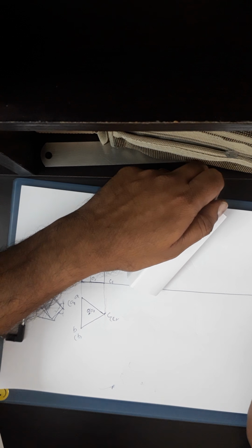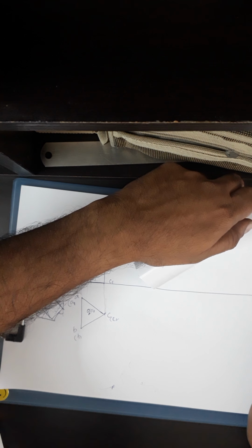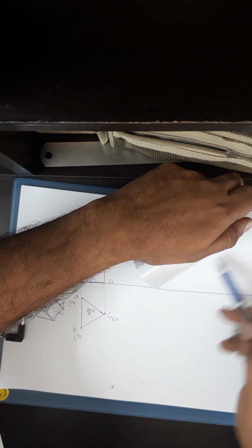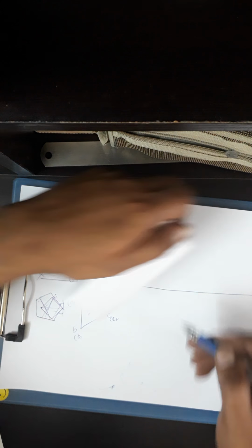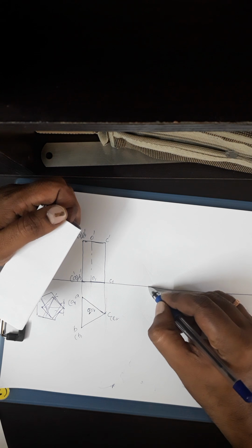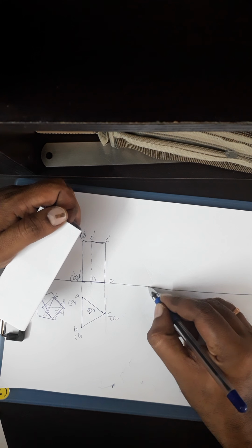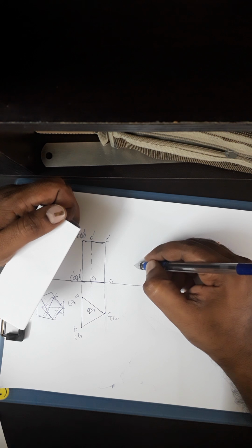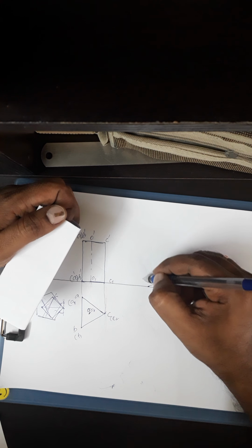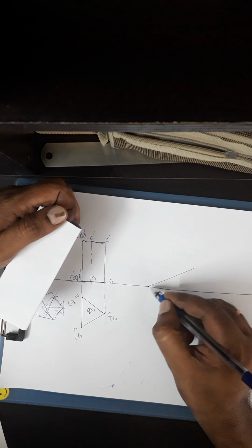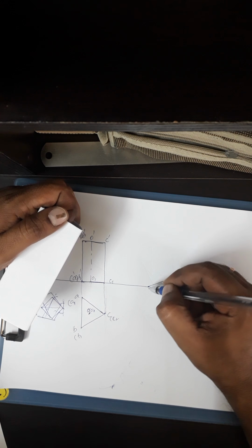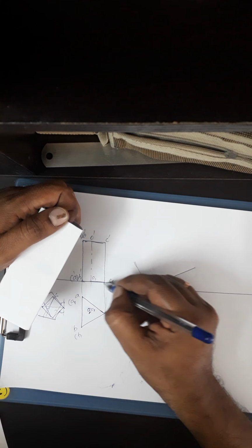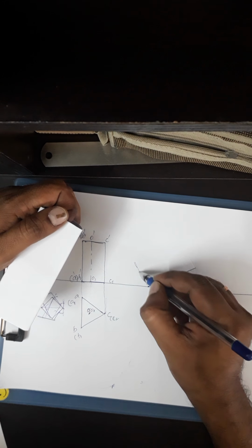I'll redraw that. In that case, the axis is inclined at 30 degrees, this base will be inclined at 60 degrees, or these longer edges will be inclined at the same inclination with the axis. I can start this drawing with CC1 inclined at 30 degrees, or I can start drawing the view with the base inclined at 60 degrees. Then automatically this will be inclined at 30 degrees to the vertical. If I draw a line perpendicular to this, because the base will be perpendicular to this, I will take that same height and transfer it here.